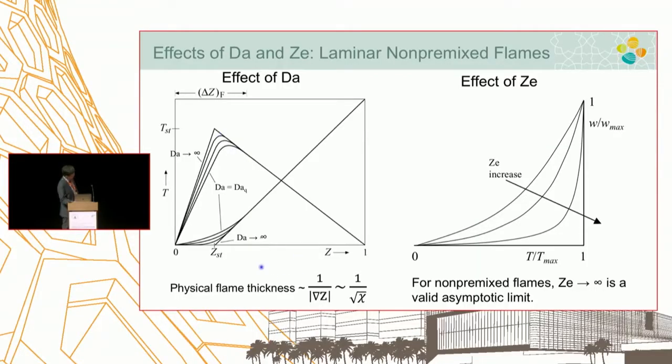As a result, not all the reactants are completely burned, and they start leaking. So that's the fundamental thing. Once you start doing that, this is fed back into the activation energy, into the reaction rate, and if you have a significant amount of drop, then the flame cannot sustain itself, and extinction happens.